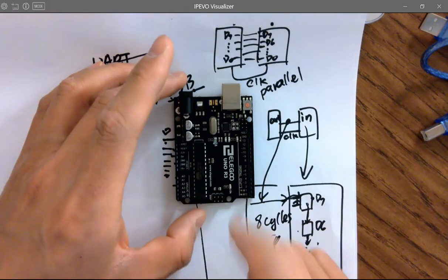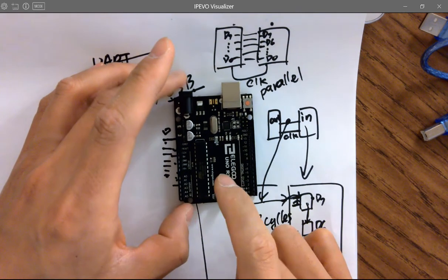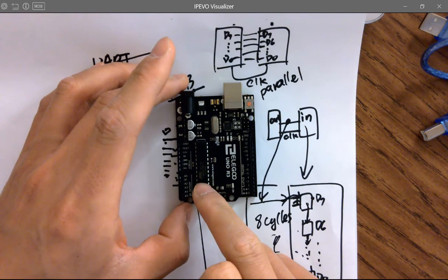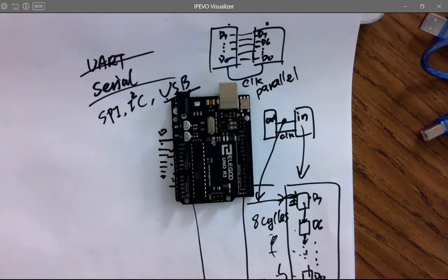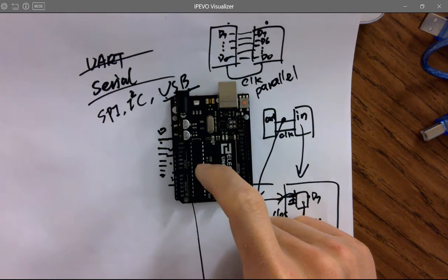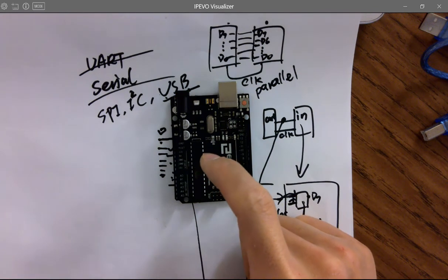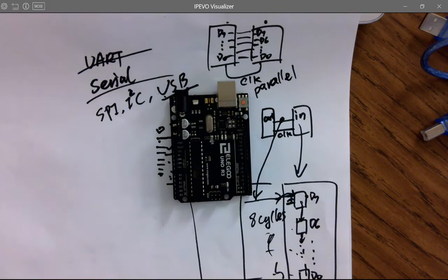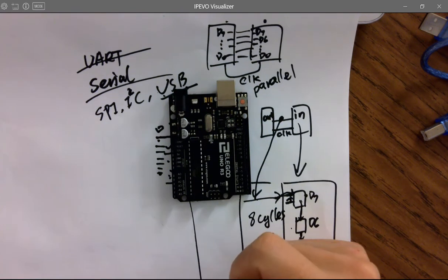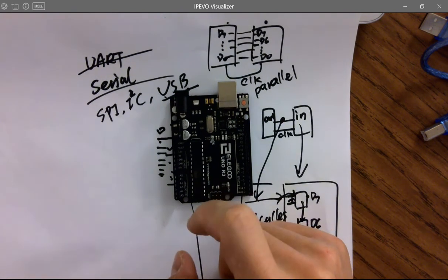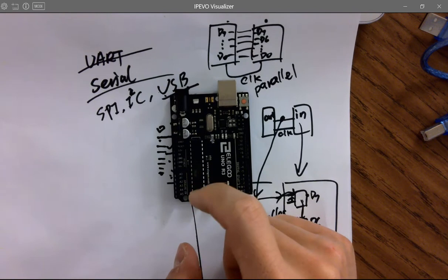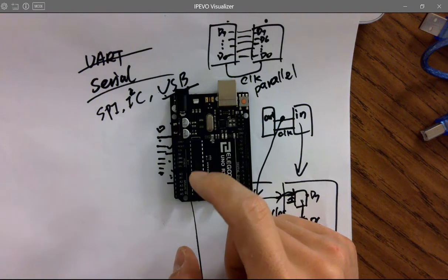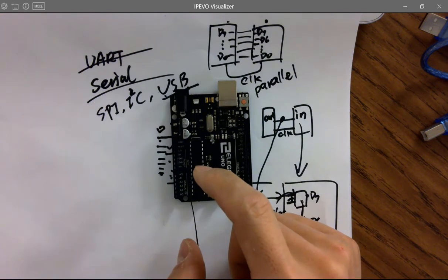Another thing is, because this is a mixed signal design, it's not a pure digital chip. It also has ADCs inside. It's a SAR ADC actually. You guys have designed a similar one in your class. And so the ADCs have op-amps and all the analog components, which cannot be fabricated using the newest technologies.